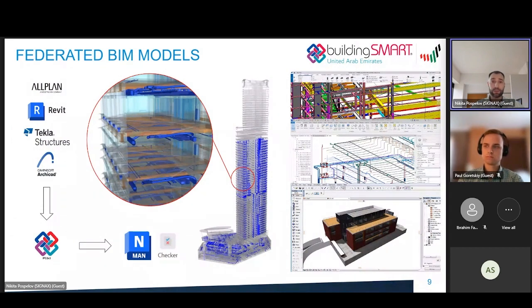Nowadays, it has become a standard that we have to cooperate and collaborate with stakeholders and their data generated from various sources. IFC format plays the main role in that process. Our BIM engineers and coordinators collect subcontractors' model files from different software suites exported to IFC format. Or we do that export process ourselves in case of in-house development. After that, we are ready to coordinate multiple disciplines and start automated model audits, including parameter checks. Audit settings are prepared in a convenient table format based on project exchange information requirements and the BIM execution plan.